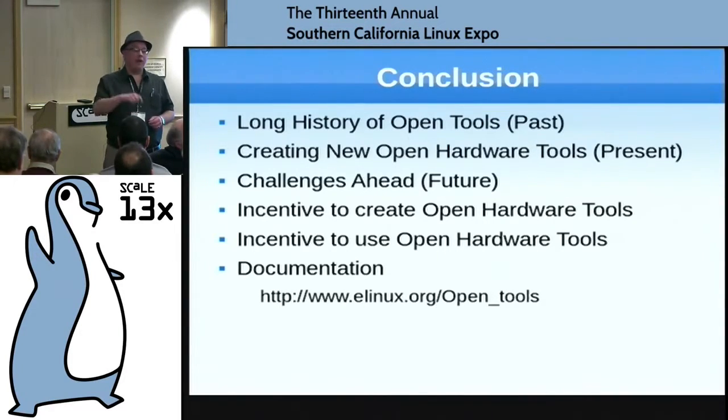Yes, because the reference design is only a guide. Usually it's done as a block diagram, and it's not a physical implementation. Now, if you copy their reference design exactly and put it directly on there, then that would be an issue. That's the biggest thing, because you're copying their reference design. If you're just copying a design note that says, be sure to use a 12 picofarad cap on this signal, that's not an issue.